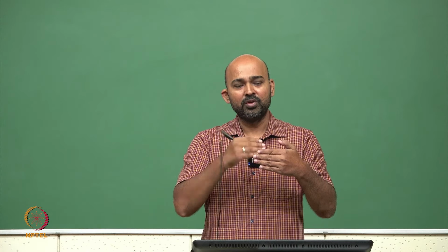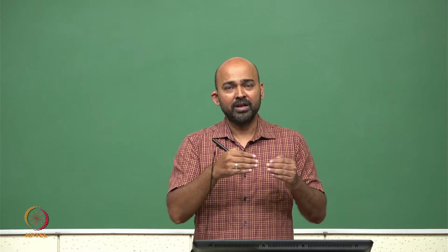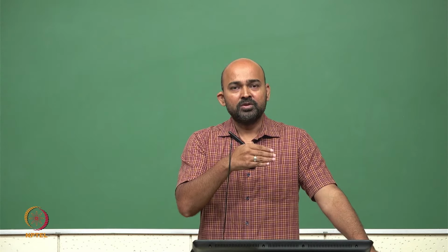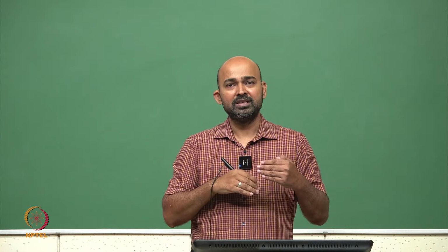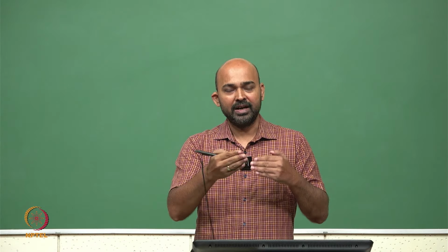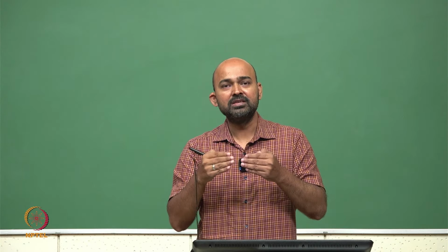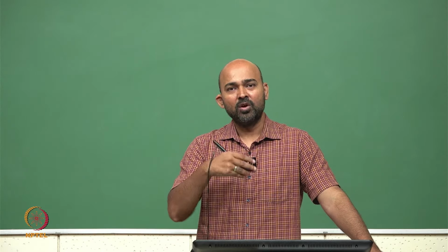Because of that, these two traces are having certain amount of capacitance, and these two metallic traces act like a metallic plate of a capacitor. In between whatever we have, that act like a dielectric. So because of this capacitance, one signal is switching, let's say, at high speed. This voltage will be coupled to the another trace, and that trace will also see the effect of having this signal switching at the very high speed. So this produces something called crosstalk.